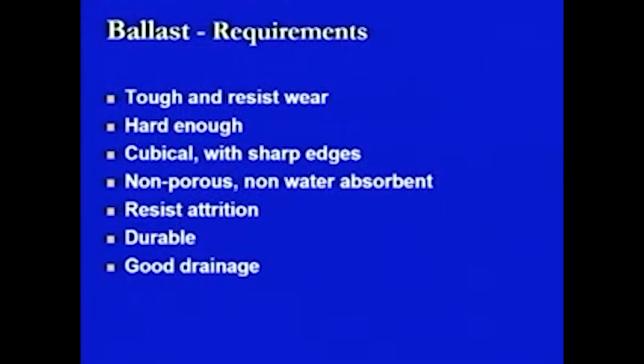Further, as we have discussed before also, it should have a good drainage property. The good drainage property is required so as to remove the chances of flooding. If there are chances of flooding, then it may take the material along with it, or there are chances that slowly and slowly the material will lose its strength. In both the cases, the track will lose its strength and it is going to be harmful in terms of the stability of the track, and there are chances that some mishap may take place as soon as the heavy loads start passing over such types of sections.